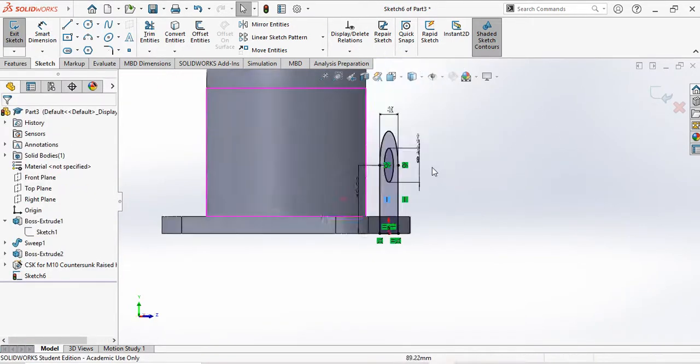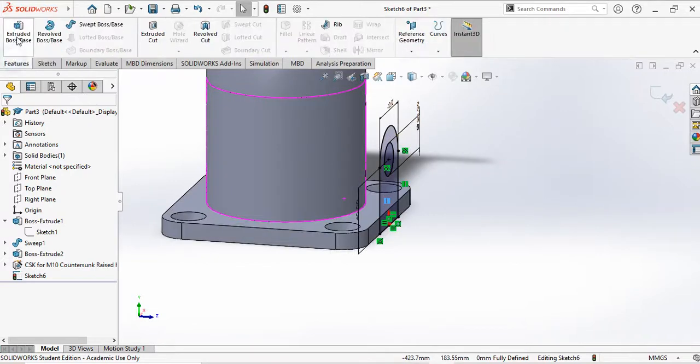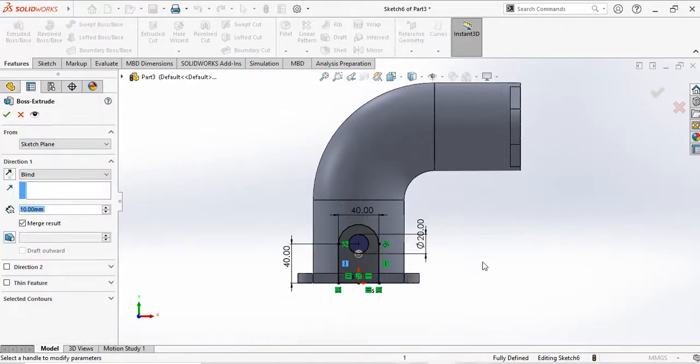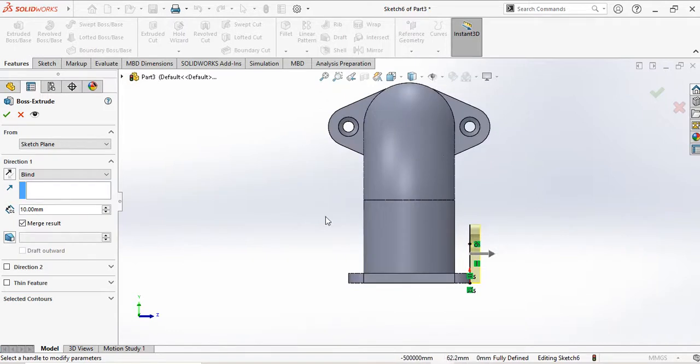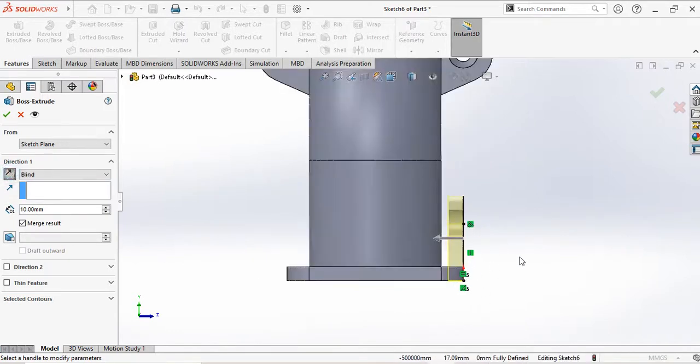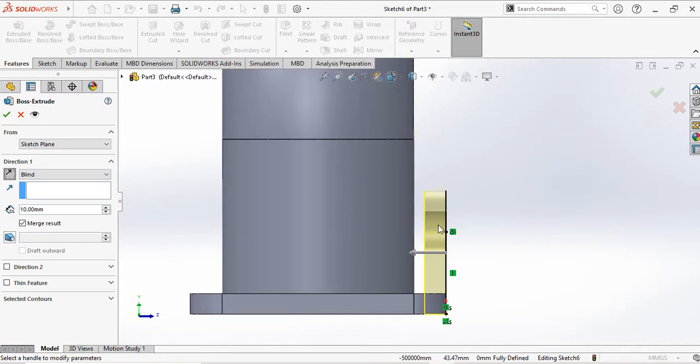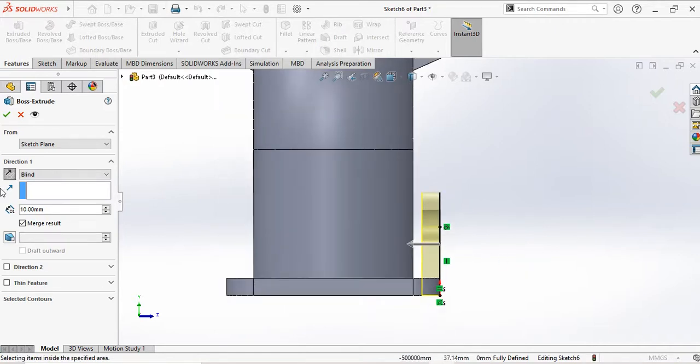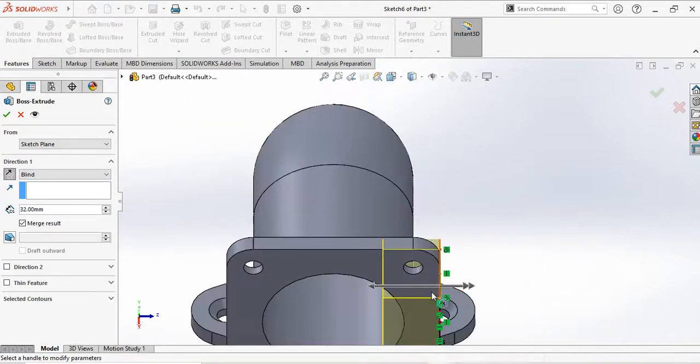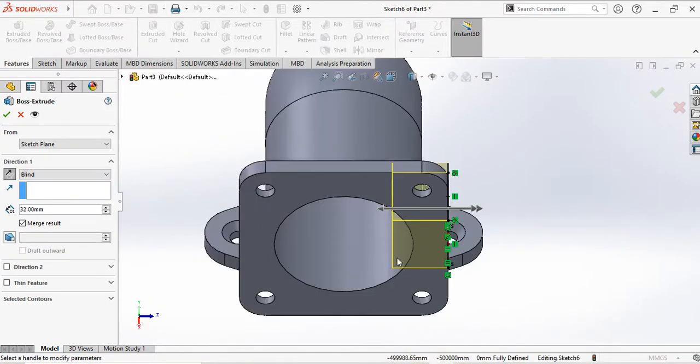Okay, now we're going to extrude. How much are we going to extrude? Remember, flip the direction. We need to extrude until it touches the curved surface and it will stop. But if we just use the feature with the option blind, what happens? We will have additional extrude over here. Inside here is no longer fully, completely hollow.